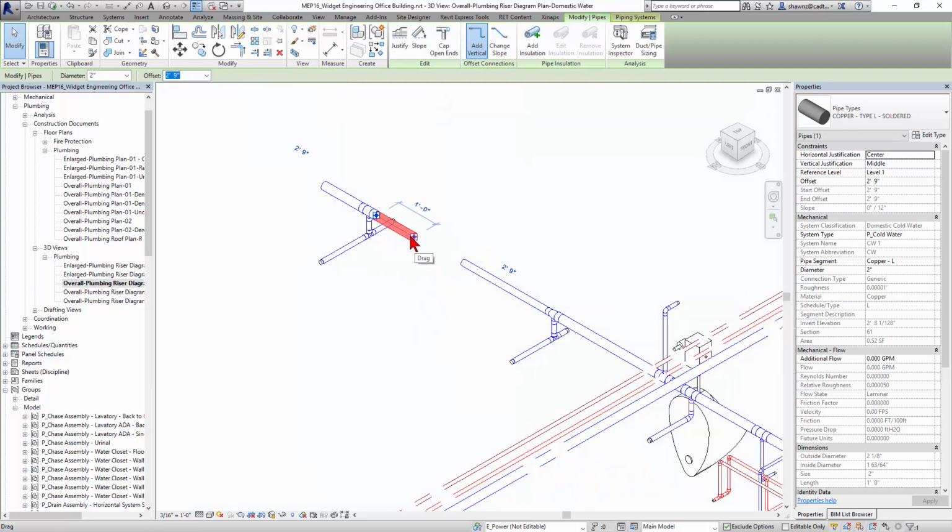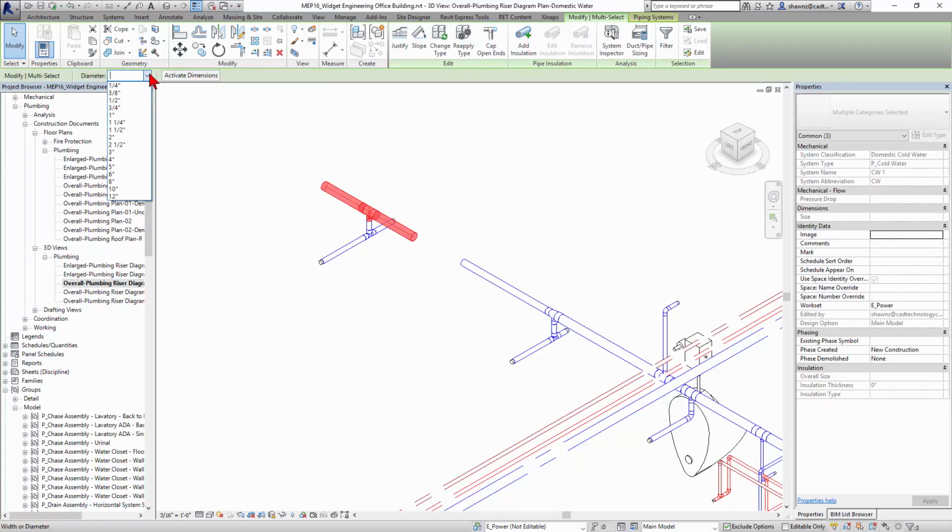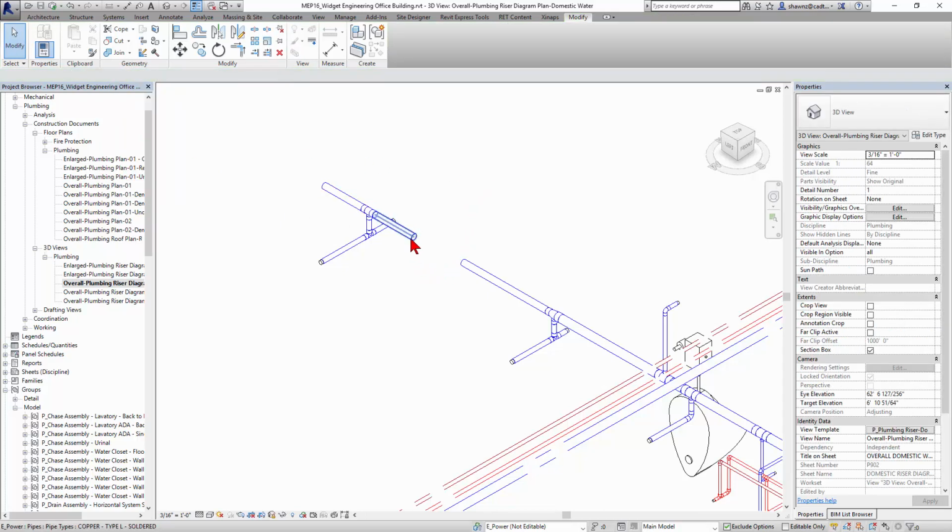These right here, I want these also to turn into 1.5-inch fittings. So let's go ahead and make that change right now. I'm going to grab both of these on each side. Let's see, maybe I can grab this fitting in the middle. Will it let me do that? Yeah, let's choose 1.5 and see what it does. So it's made that change, no big deal.